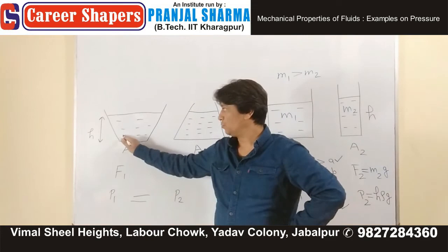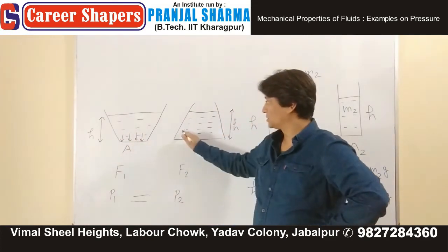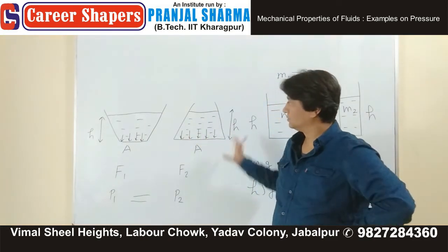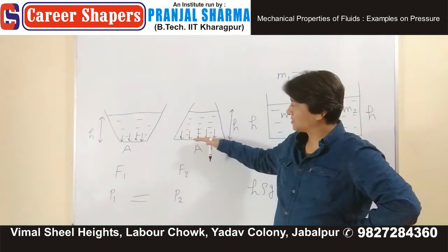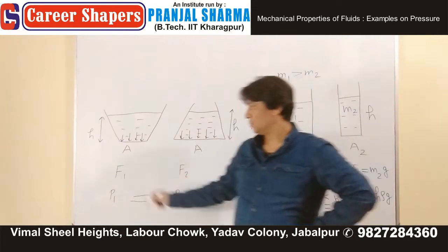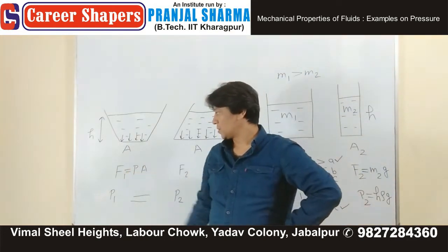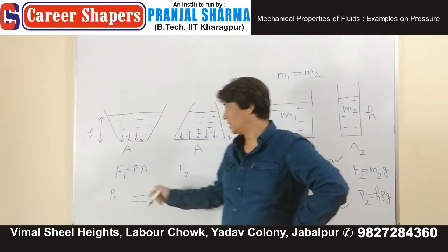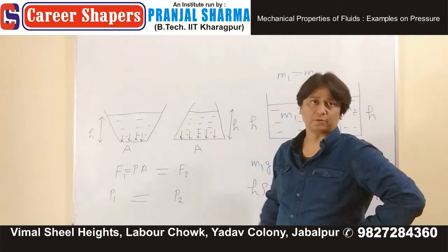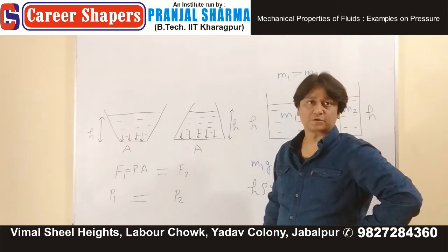Now, what is force? The force will be coming like this. The entire liquid is pressing the base down with the force of F2. But what is force? Pressure into area. You've got the same pressure, you've got the same area, and therefore F1 is equal to F2. They both have the same force.